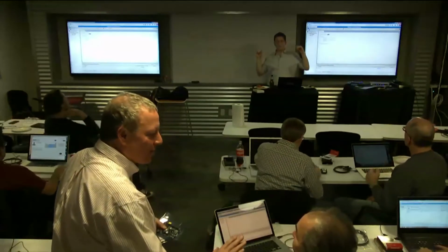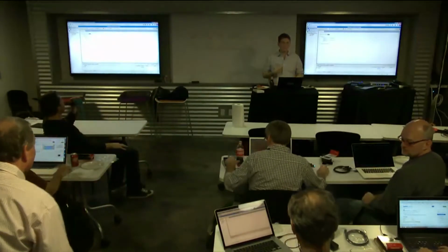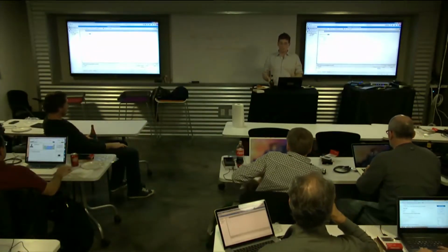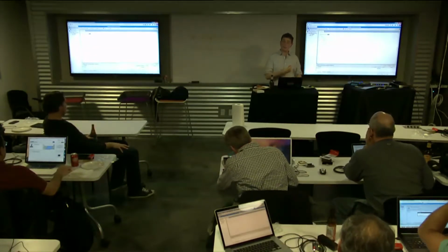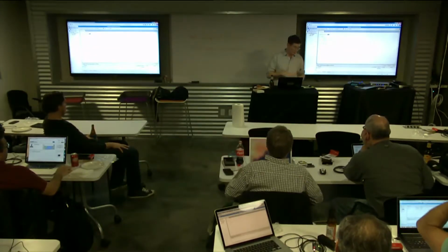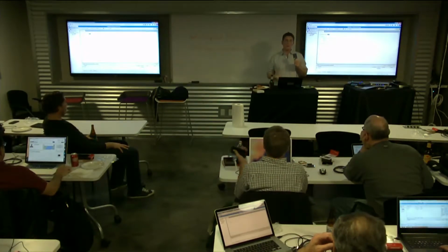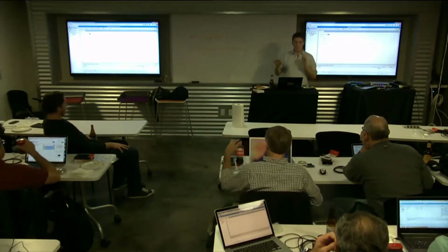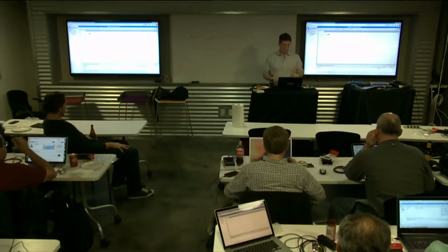So there's this thing called virtual serial ports in microcontrollers. It allows you to send a stream of text back up to the computer from the microcontroller. In this case, all of these boards are equipped with a virtual serial port by default. If you just use a printf statement, whatever you dump into that printf statement will magically show up on your computer. I'm going to show you how to use that magic for awesomeness.